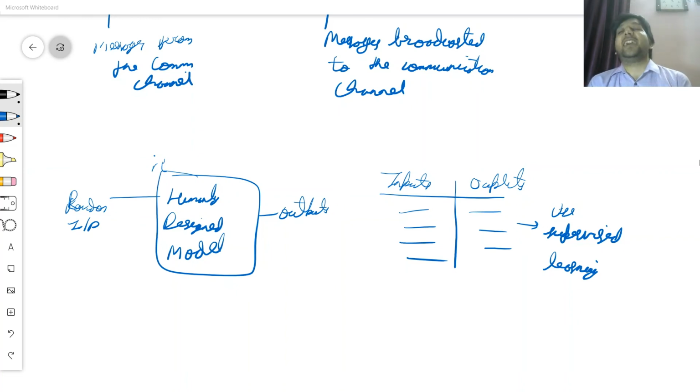Of course, each one of them will have a heavy bias of the algorithm it's coming from. If it's coming from teleoperation, it will have a bias towards the operator who was operating it. If it's coming from a potential field algorithm or probabilistic roadmap, it will have all the bias towards those methods. If it's coming from a natural everyday scenario, there's a bias in how humans operate and how robots operate, which are different because of the kinematics. If it's from a virtual reality system, how you react is different. Even in virtual reality, you'll bang into obstacles and really enjoy it, so it has a very high bias towards that.